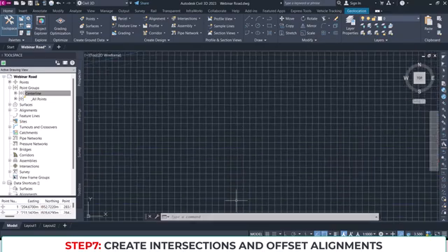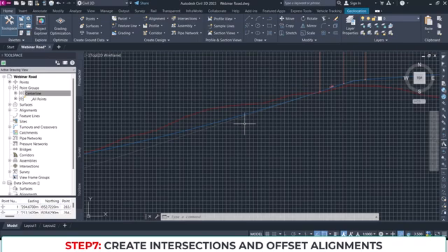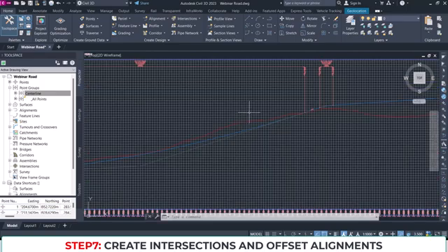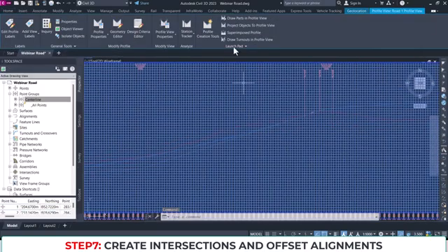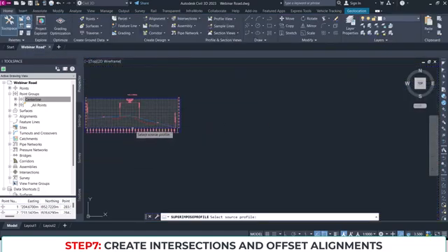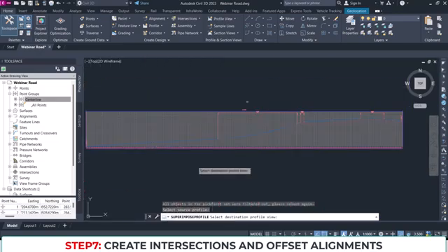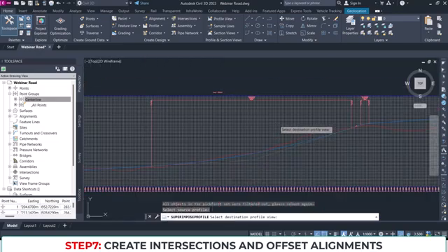You can see. You don't have to do it manually and keep checking it. There's a way you can bring in that road 2 profile here and see how it is looking. So let's just do that. If you click on this grid anywhere, you'll find somewhere up here that shows you superimpose profile. Then go to road 2 and click the design profile. Then come back to this place and click anywhere on the grid.